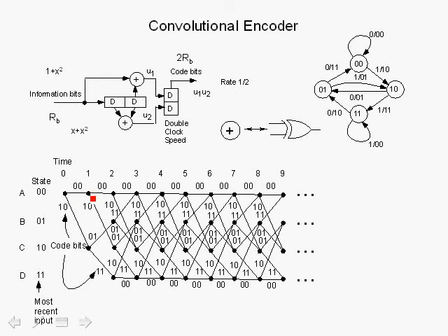This is actually shown here. As long as we get zeros, we just stay in the 0, 0 state. If we input a 1, the 1 gets shifted in, and the 0 shifts over here, we get the next state as 1, 0. So we jump from this node to state 1, 0 over here. That's when we have a 1 as an input.